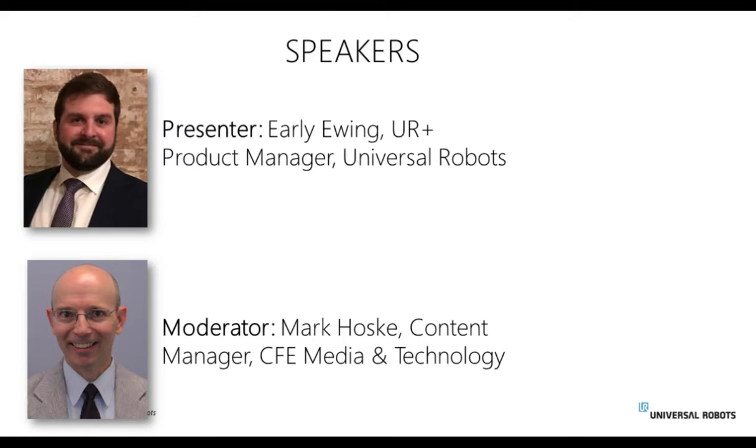What the robot helps you do is implement those engineering controls, such as force and power limiting, speed limiting of the robot, setting up safety planes, et cetera, to help, at a lower cost and investment, implement those controls to satisfy the needs dictated by that risk assessment.